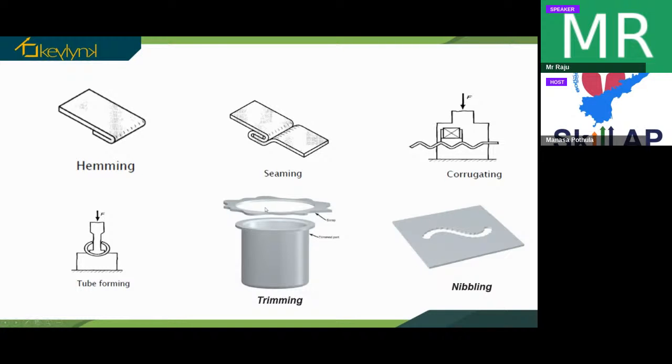What is deep drawing process? We'll learn later. When the punch goes inside and the die presses it, this structure will form. But the blank will be stretched in such a way that it will leave some burrs like this, or some extended irregular shapes at the top end of the part. So what we do is we cut the part and we take it. So we are cutting the sheet metal here. So it's a shearing process. It's not a bending process, it's a shearing process. That is, we are cutting the extra part, the irregular part, from the real part.